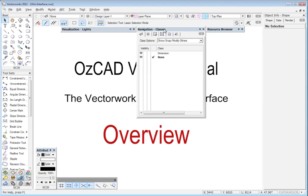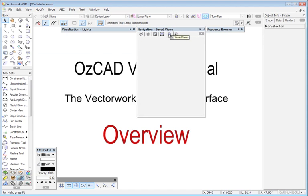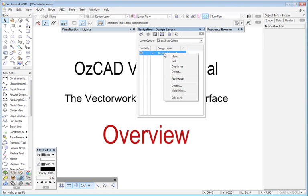The navigation palette, this allows you to interactively change class visibility and layer visibility and directly access your saved sheets, your viewports, saved views, and any references that you have. And you can also jump straight to some other functionality by right-clicking on any of the items that are displayed in the navigation palette. For example, if I right-click here, I can create a new layer, edit this layer, duplicate the layer, delete it, activate it, and so on.